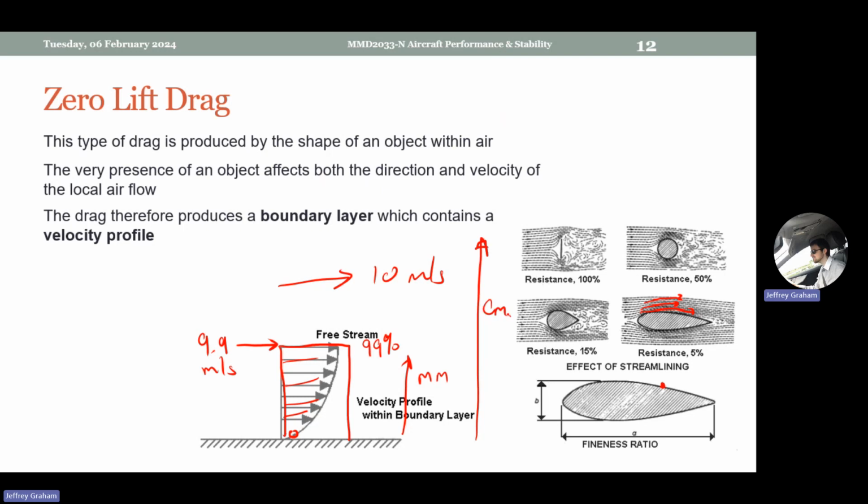So basically, I think it goes anywhere up to twice the size, maybe 3 times the size. So obviously, the bigger the boundary layer, the more disturbance we're going to produce in our airflow, the less lift we're going to get from our wings, the more drag we're producing.